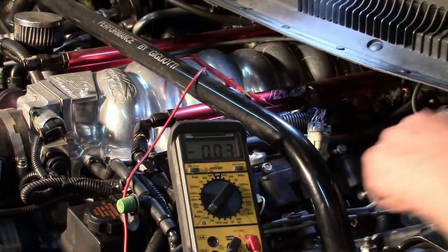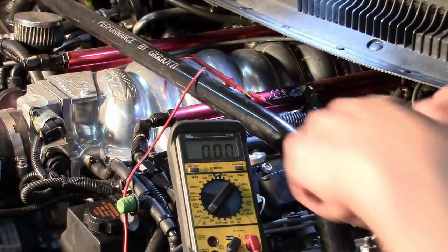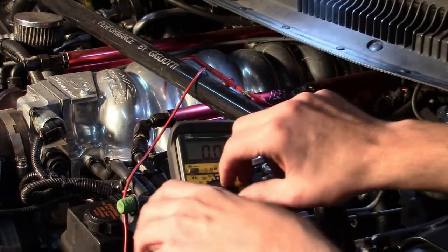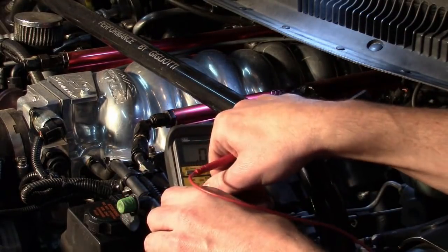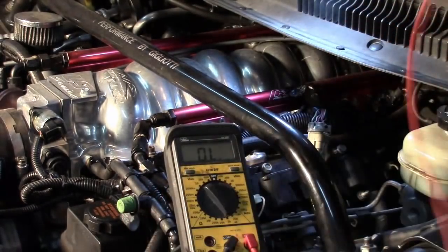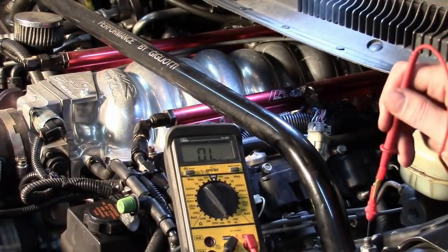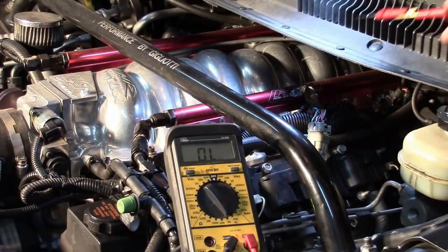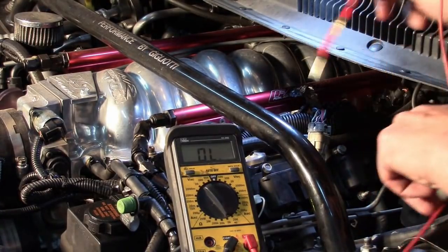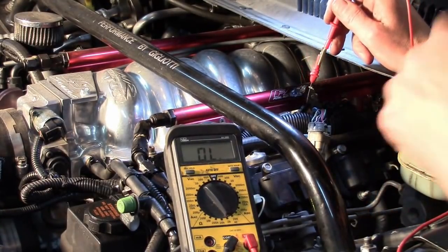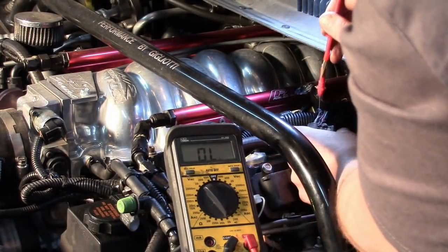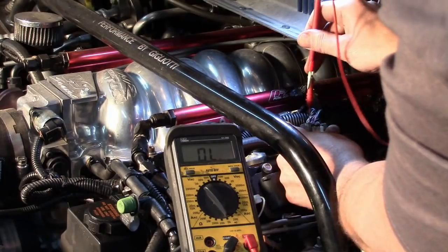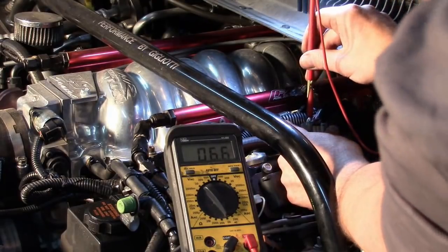The black wire. So how am I going to determine that black wire, which I believe is ground, I'm not sure? What I'm going to do is test continuity. Okay, so I'm going to put a noise signal on here. So we're doing a continuity test. When I find ground, of course, we're going to be able to easily detect it. Now, just because I find a ground here, it doesn't guarantee that it is that shared ground for everything, but this black wire I kind of like. Okay, we see that we have it there.